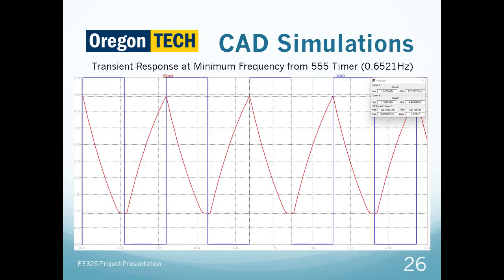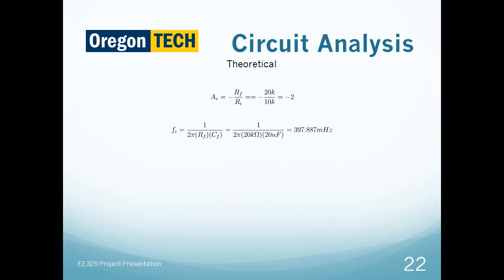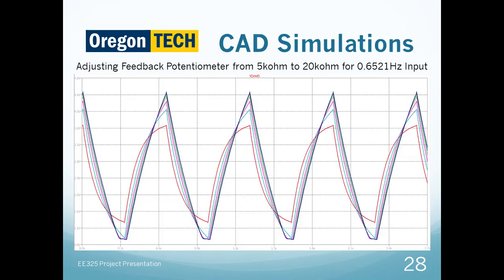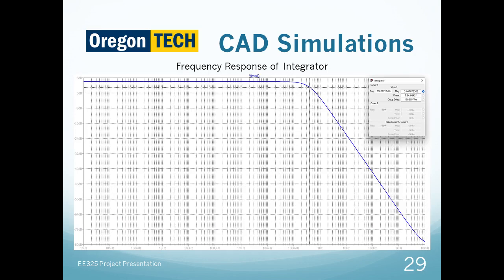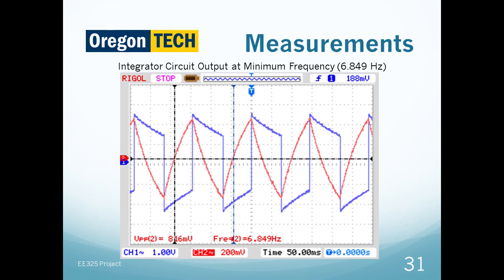The square wave output from the 555 timer is passed into an integrator. The integrator corner frequency of 0.398 Hz ensures that even the lowest selected frequency is transformed into a triangle wave with a modest slope. The integrator operated well at the low end of the clock frequency. The reduction in gain as the clock frequency increased was not considered prior to implementation.